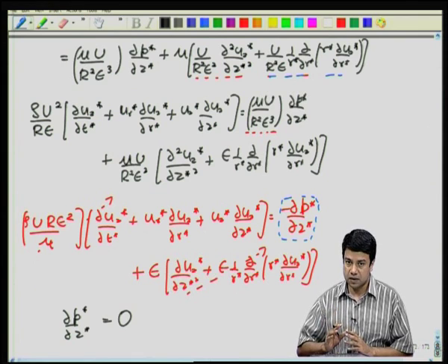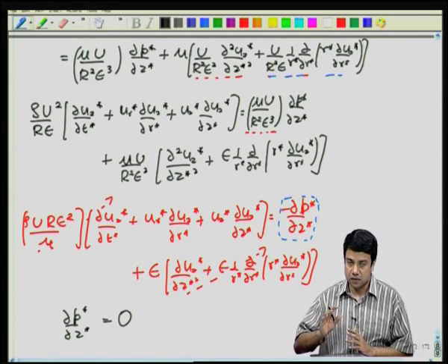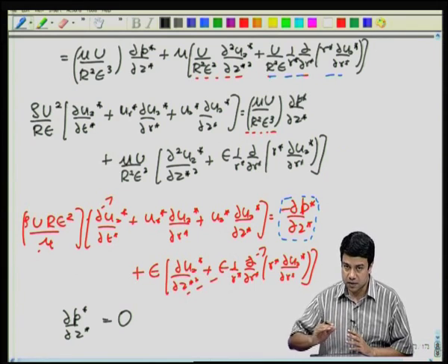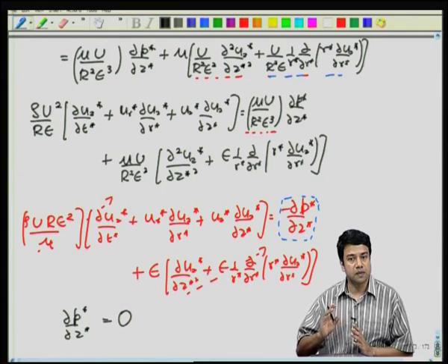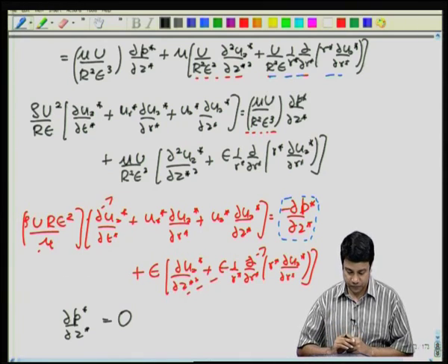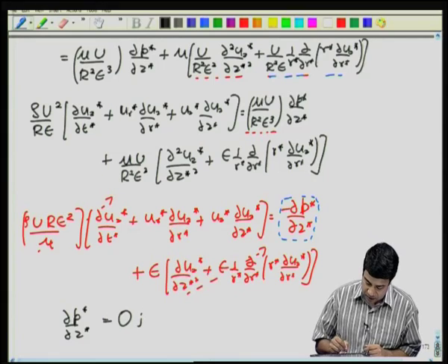We will see a little later, this is a common feature. In all cases where the velocity in the streamwise direction is large compared to the velocity in the perpendicular direction, you will find that the pressure gradient perpendicular to the flow, okay, to the largest velocity component is always 0. So, this gives us the 3 scaled mass momentum conservation equations. Okay. This was for the z direction.